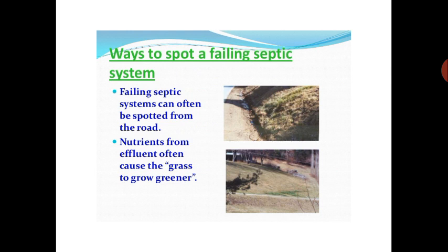Some of the tanks, if you design them on the side of the roads, then it is a big problem, because through the side of the roads your side drains will be there, and the water will carry all those things. It is better to avoid septic tanks near the roads.